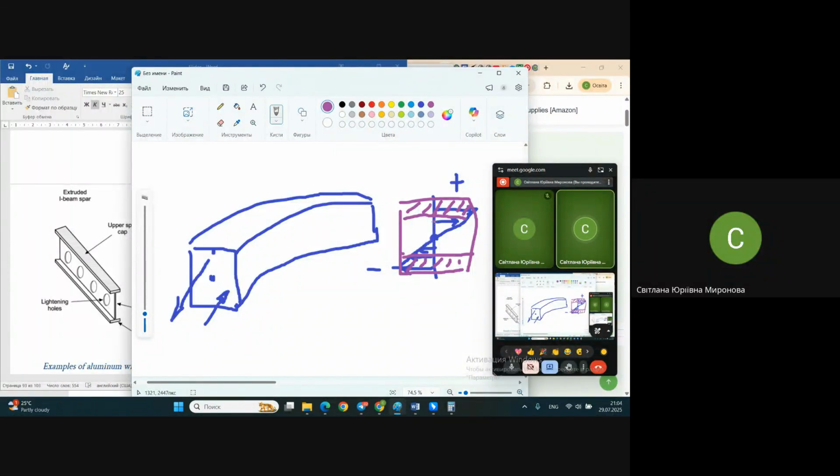And I hope you do remember what I already said about designers. Designers of airplanes are always crazy about minimizing weight. Each element of the structure should work effectively, receiving the loads, counteracting the external loads. You shouldn't have any structural element on board which doesn't work, because it has weight. The weight of this element results in additional fuel for transporting this element, which doesn't work.